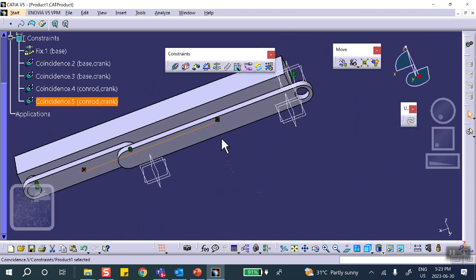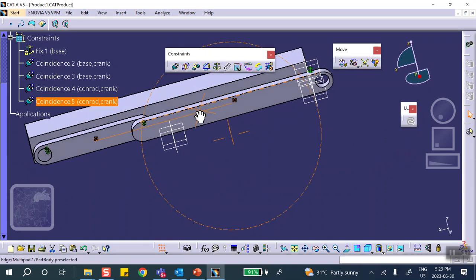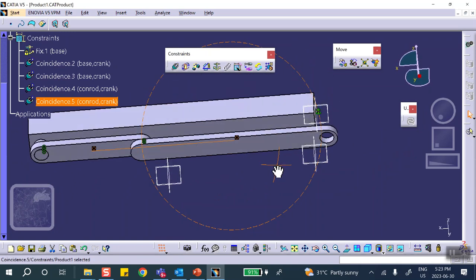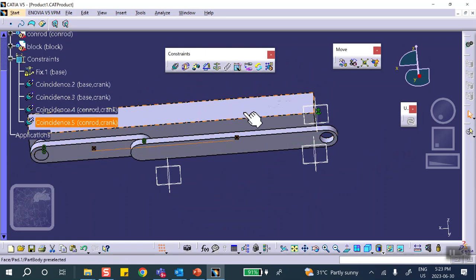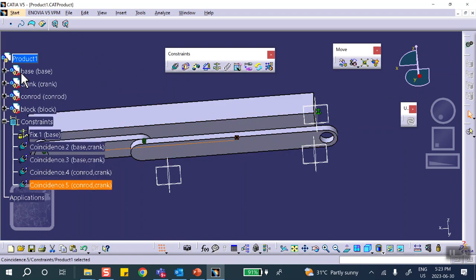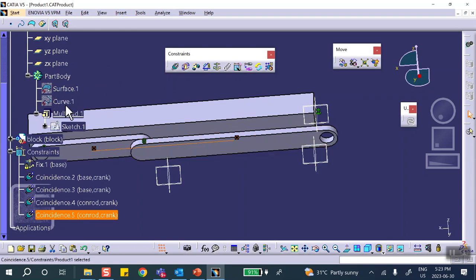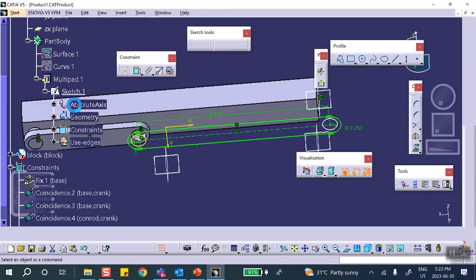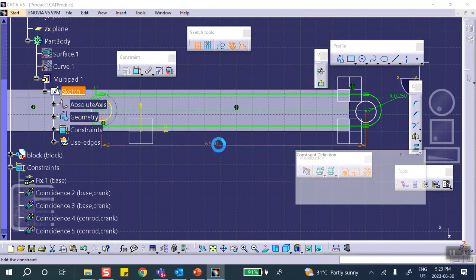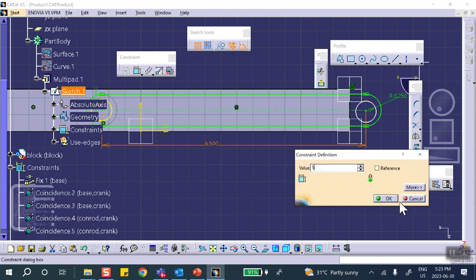Okay. This is too long, I think, because notice that I didn't want it to be that long, so let me go ahead and change one of these dimensions. We can go actually to, this was the Conrod, right? So we go to the Conrod, and I believe it was this sketch, right? Yeah. Okay, so let me change this thing to maybe 5.